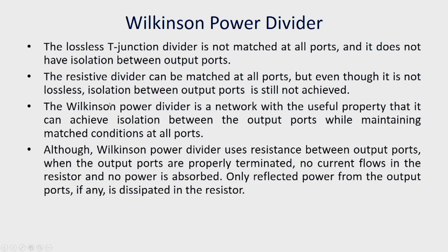Now, Wilkinson power divider, we will see it will use resistance between the output ports, but when the output ports are properly terminated, no current will flow in this resistor. So, essentially there will not be any power dissipation in that resistor when the ports are properly terminated.